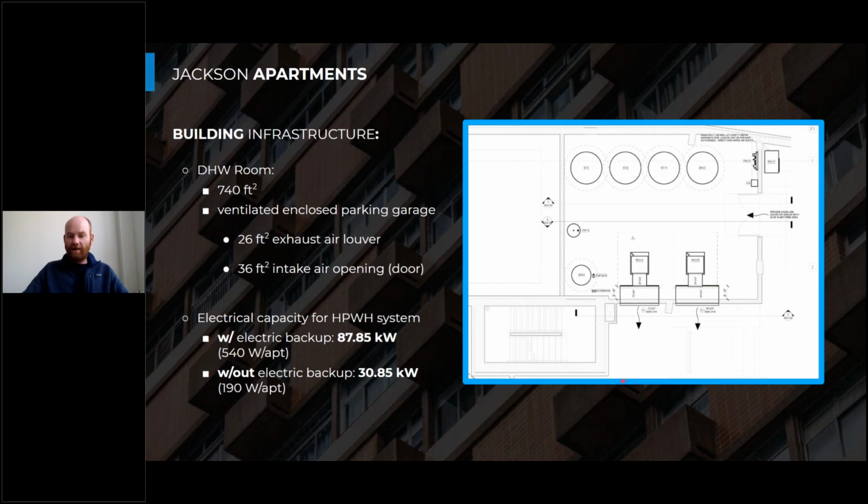And what you can't see here is there's a garage exhaust fan system sitting right about here. So as we're drawing air from levels above, it gets warmed up, then it enters through these ventilated double doors. They're just essentially chain link doors. It gets drawn into that heat pump. The heat pump extracts the heat, puts it into our storage tanks, and then we blow that cool air back into the garage and direct it towards those large garage exhaust fans, which are running continuous and then peak into a higher flow rate based on toxic gases in the garage.